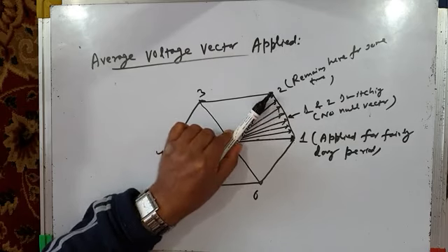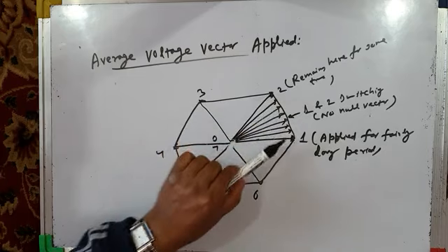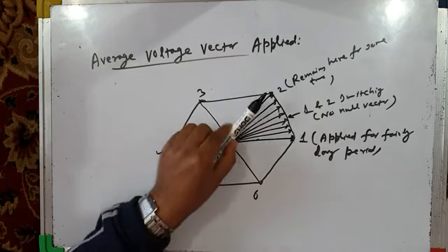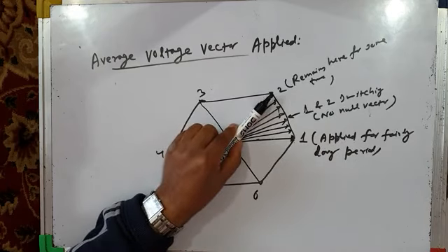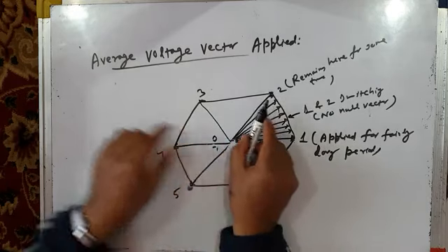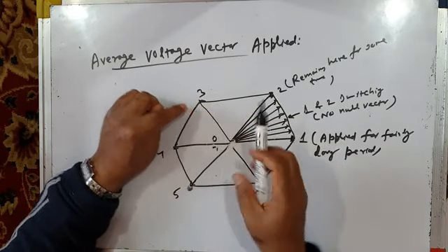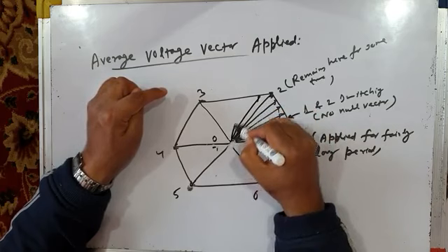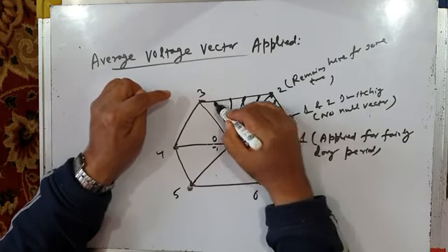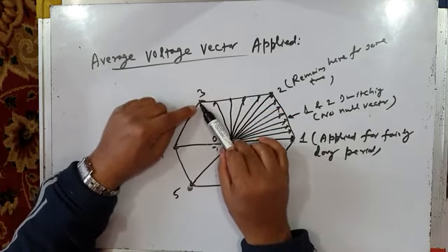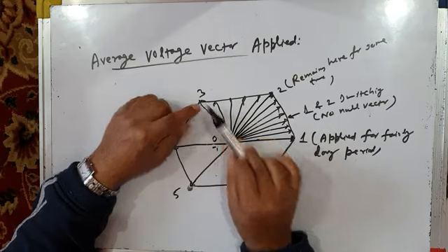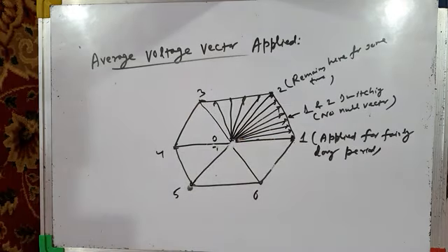And then it applies active vector 2 for fairly longer time. Okay, this is in sector 1, and in sector 2, active vector 2 is applied for some time, no switching occurs, and then there is switching between active vector 2 and active vector 3, no null vector is applied, and your rotating reference vector moves along the hexagonal trajectory like this, and then active vector 3 is applied again for some fairly longer time, and this repeats in all the sectors.